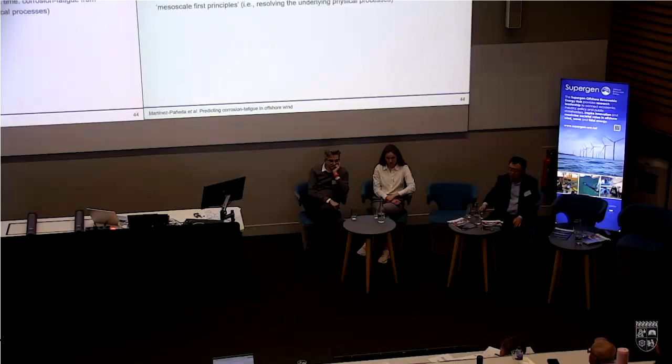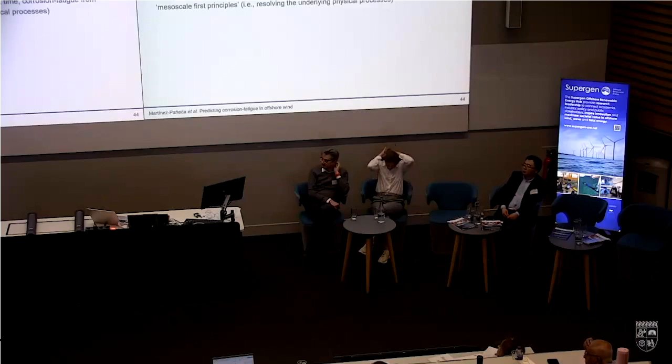And the opportunity more specifically comes from this new class of multi-physics phase field models that allow you to simulate this kind of corrosion fatigue directly from first principles, right? Simulating directly and explicitly those underlying physical processes, so that you don't have to make an assumption, you don't have to come up with some magic knockdown factors and that kind of stuff.